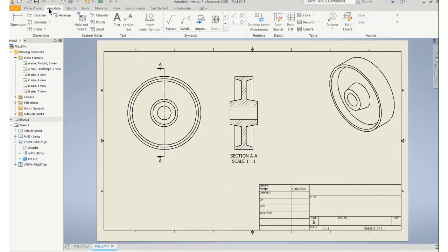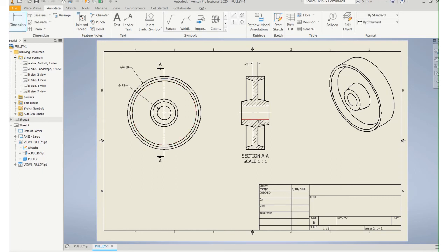So now we have a perfect place to add our dimensions. So those lines that used to be hidden lines, they're now object lines, so I can freely dimension to those. Add all my dimensions. Now there's a lot of diameters here. If you just put all the diameters on there, it's okay, but it's really hard to tell. So for example, if you put a diameter on this without the right side view, it doesn't really mean a whole lot. So really a better way to do that is use the section view to call out some of those diameters. Like, what is this line here? Well, we know it lines up with that, but it makes a lot more sense if you dimension it that way.